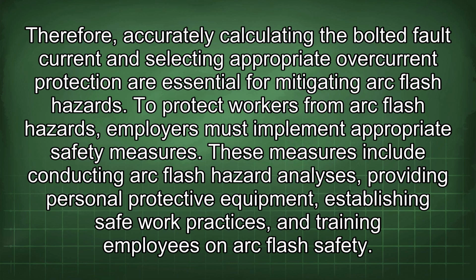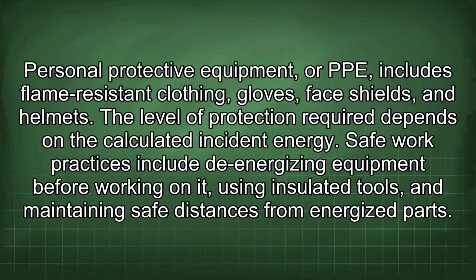To protect workers from arc flash hazards, employers must implement appropriate safety measures. These measures include conducting arc flash hazard analyses, providing personal protective equipment, establishing safe work practices, and training employees on arc flash safety. Personal protective equipment, or PPE, includes flame-resistant clothing, gloves, face shields, and helmets.